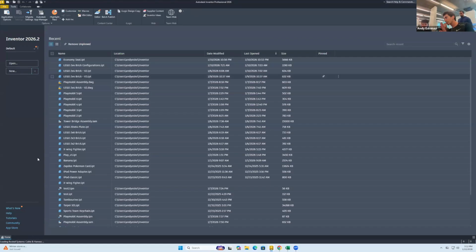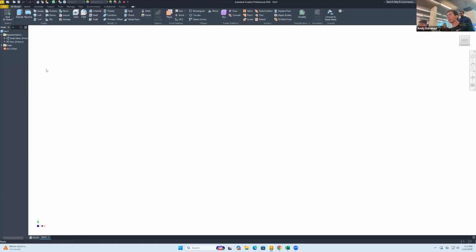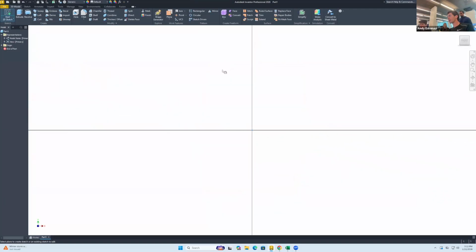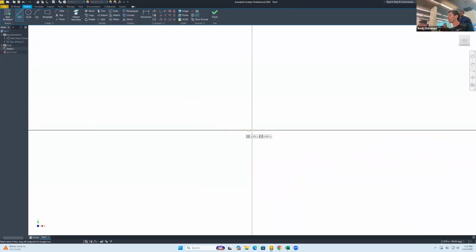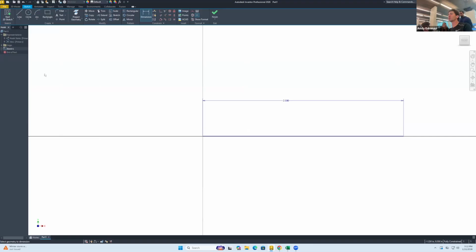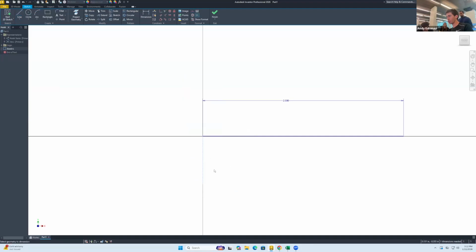And now it's gonna delete opens for a second. And we'll do a sketch on one plane. And we'll start just by drawing a line that will go like that. And let me give it a dimension D. And the units don't matter as much, but say 2 inches. So this is gonna be an extremely small trumpet. And then I'm gonna draw a line that goes like that. I'm gonna make that a construction geometry.